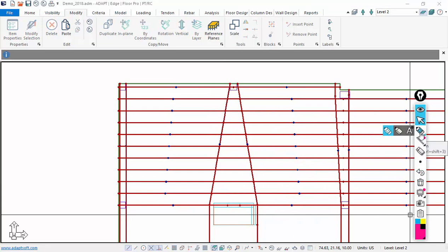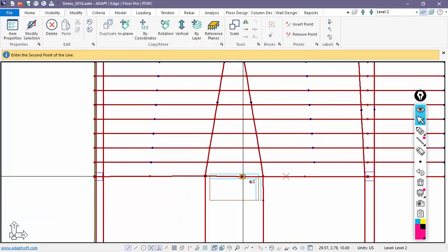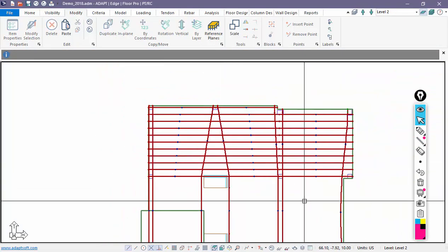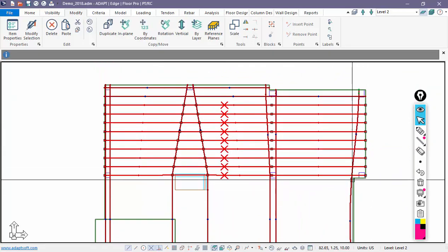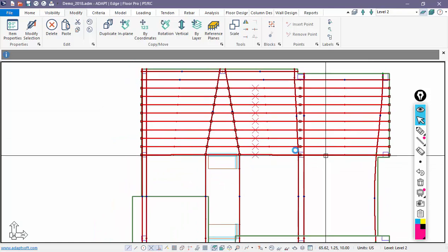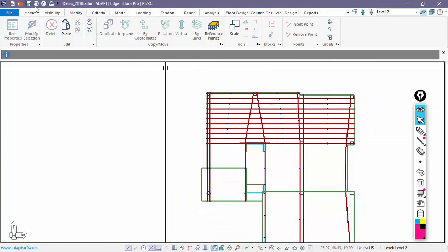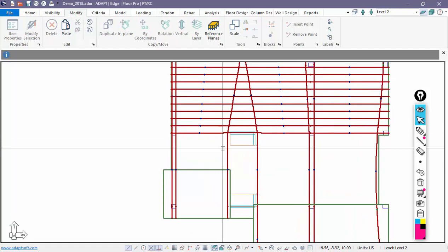I'll go ahead and draw that wedge. This is all straight in terms of the profile here for the demo. We'll do the same thing here. This will be straight over the wall. And along this path, again, these all anchor at the edge. You could again make a case this is a cantilever. However, there's a column here. It's not a true cantilever in that sense. So that's the replication of the tendon over that let's say first bay.